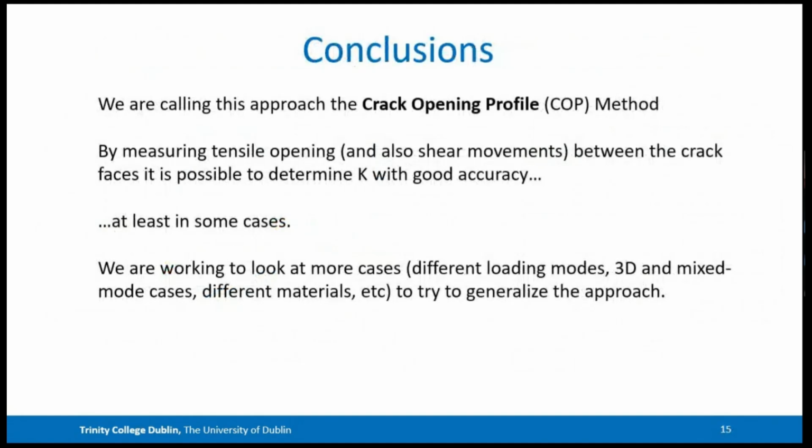So finally, we're calling this approach the crack opening profile, or COP method. And as I've said, by measuring the tensile opening and also any shear openings between the crack faces, it's possible to determine K with good accuracy, at least in the cases that we've already looked at, because there are lots of other cases to study. And so we're going to continue with this approach, making finite element models and doing experiments to try to generalize the approach so that in the future, in principle, any crack that you have anywhere, if you can see how much it's opening, you should be able to work out what the stress intensity on that crack is.